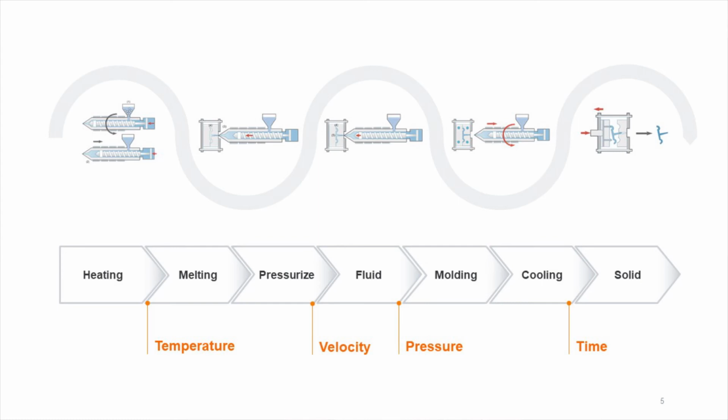solid state. Though the plastic undergoes a wide range of temperature and pressure, actually we cannot control its properties very well since there are only 4 parameters that can be set on the machine. That is, temperature, injection speed, packing pressure, and cooling time. The ideal condition is the uniform temperature and the smooth pressure profile on the plastics.